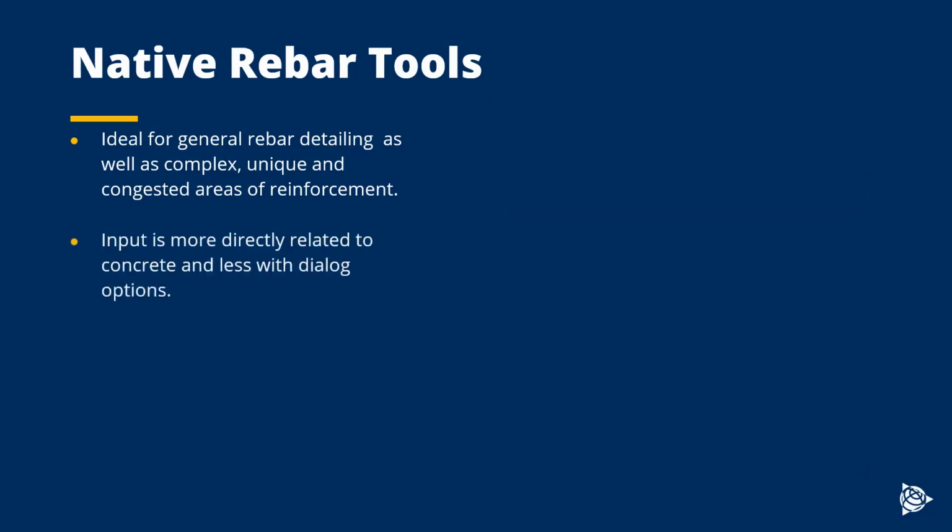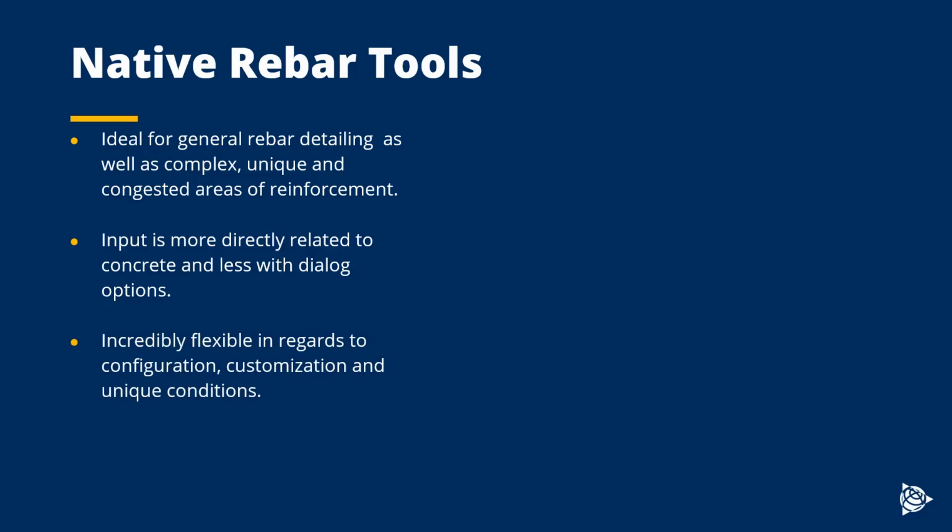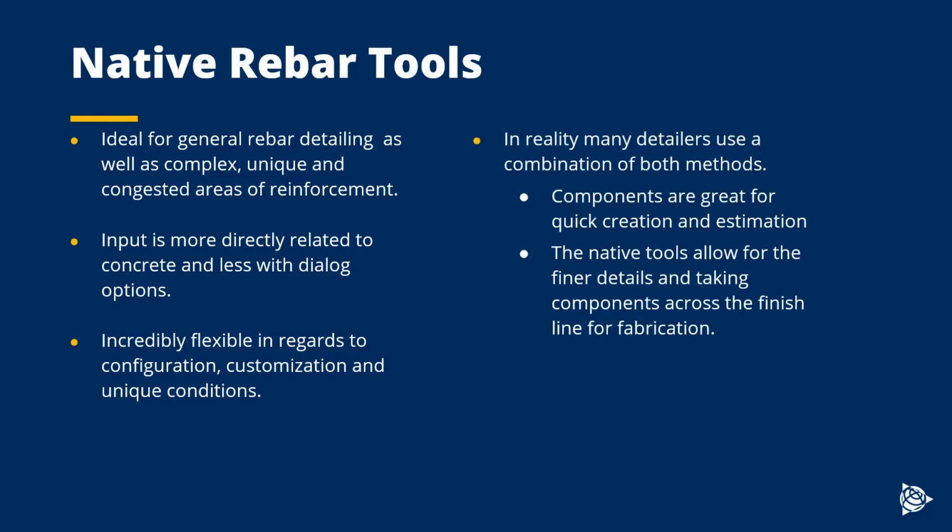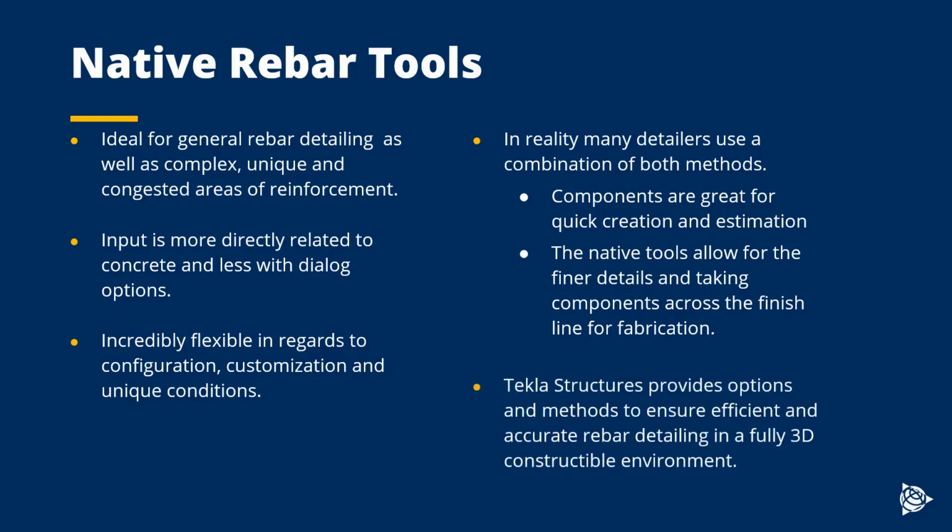The input for this type of tool is a bit more directly related to the concrete and less to do with dialog options as with the components. They are incredibly flexible tools in regards to configuration, customization of reinforcement, and unique conditions. In reality, many detailers use a combination of both methods, where components are great for quick creation and estimation, and the native tools allow for those finer details, taking the components across the finish line for fabrication level detail. The point here is that Tekla Structures provides options and methods to ensure efficient and accurate rebar detailing in a